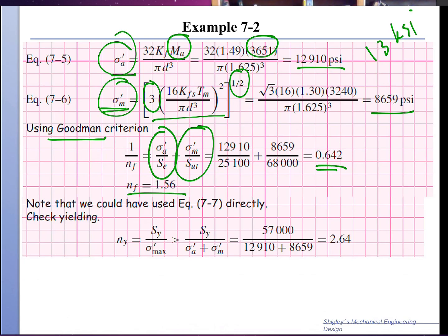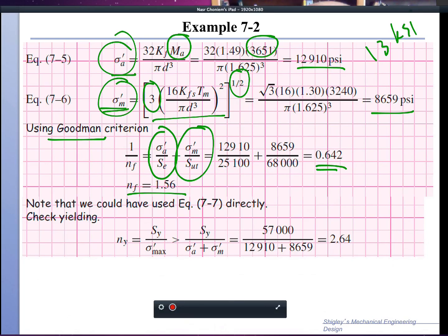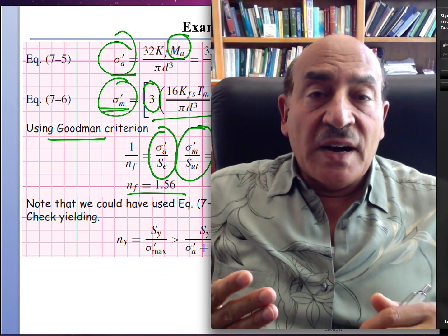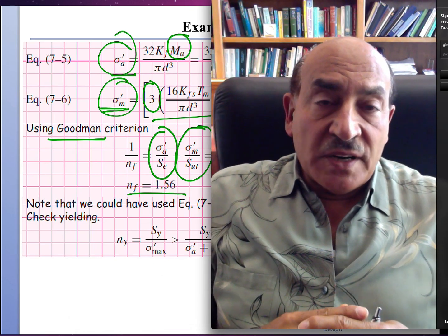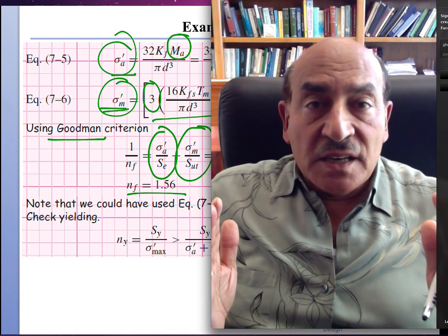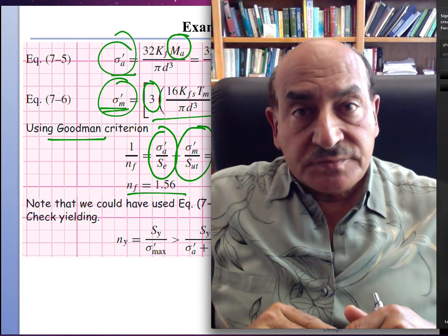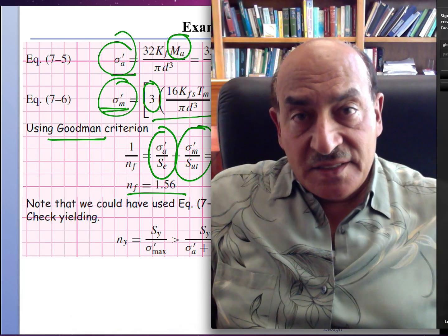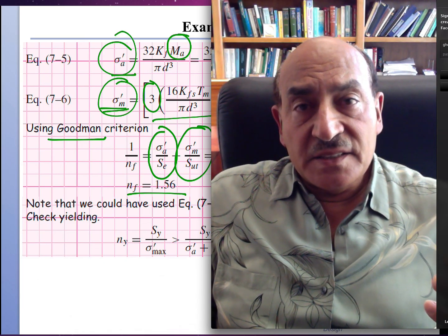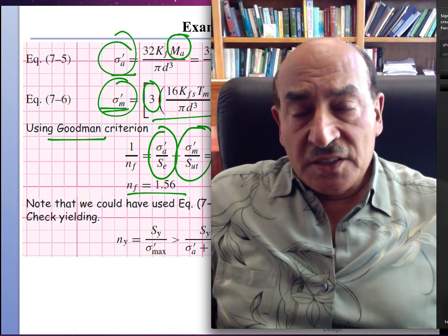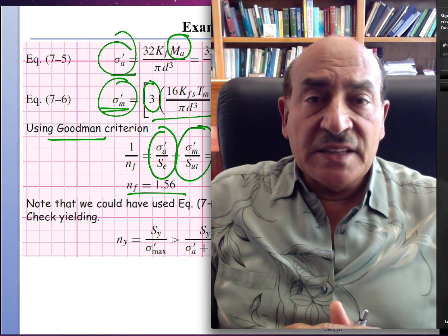From that, we can solve for the safety factor for fatigue, and find that to be 1.56. So it's above what is required, and we have satisfied the fatigue infinite lifetime requirement at this critical location I. One more thing we have to do is check to see if we will exceed the yield on the first cycle, and this is basically finding the maximum stress, alternating plus mean, and then comparing that to the yield.